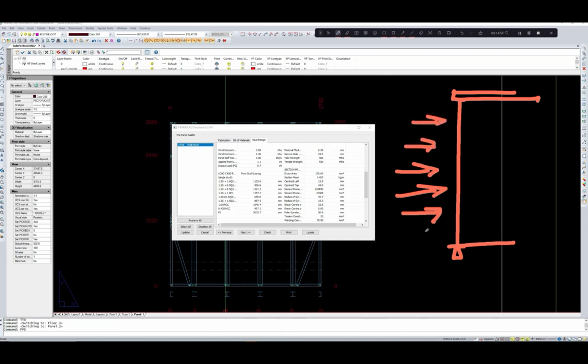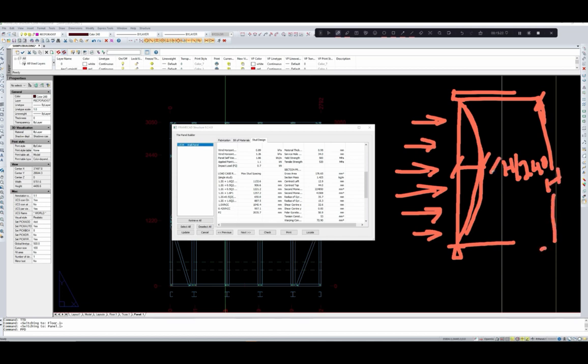The magnitude of wind load on the stud will depend upon the system. Now it will deflect like this, something like this. So this is the deflection. This deflection should not exceed h by 240, where h is this, should be less than h by 240.